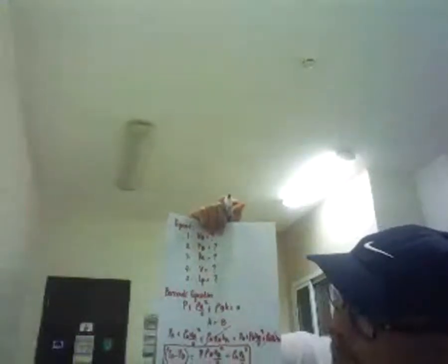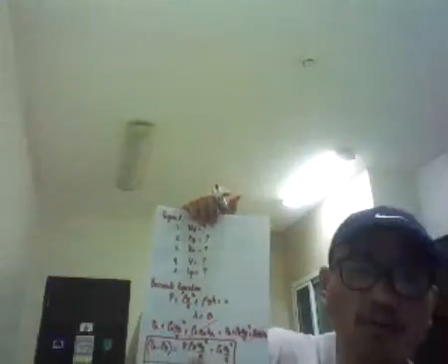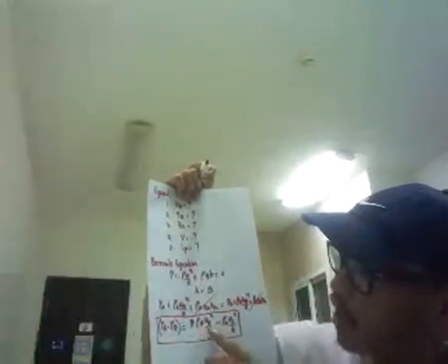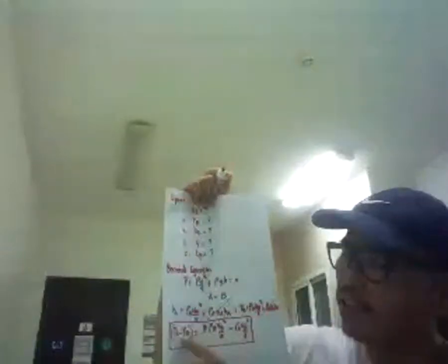Is this equation enough to solve for UB? Yes, it is. But try to look at the other quantities if they are okay already. So we have the density of water, 1,000 kilogram per cubic meter. We have the gravity, right? No, gravity is already canceled. Sorry. I love gravity, that's why 9.81. Here pressure is already identified, but we don't have pressure at the second point. So that's a problem.